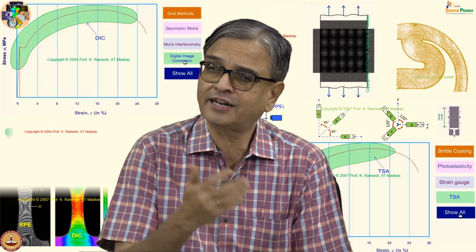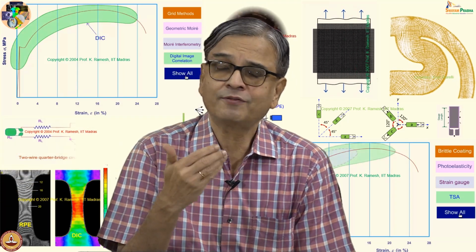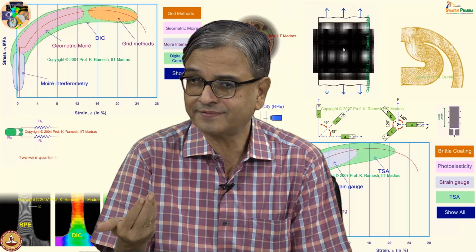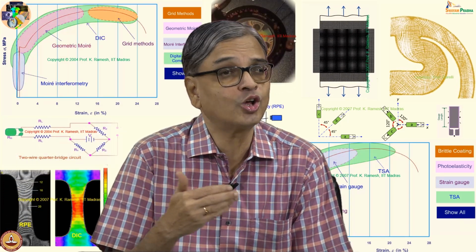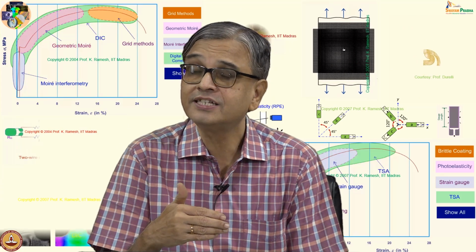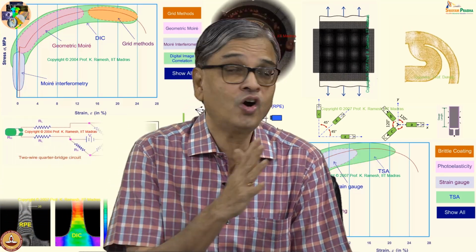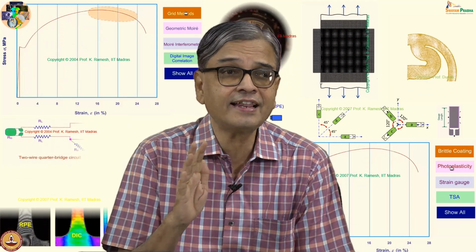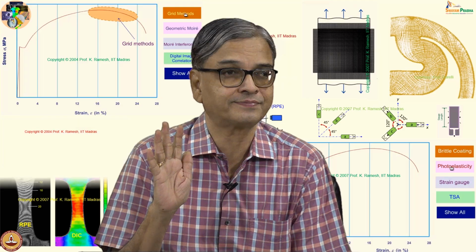When you stretch a conductor, whatever the stress introduced influences the change in the resistance. But the resistance change also can occur because of change in temperature. So, in all strain gauge measurement, you must account and segregate any effect due to temperature.